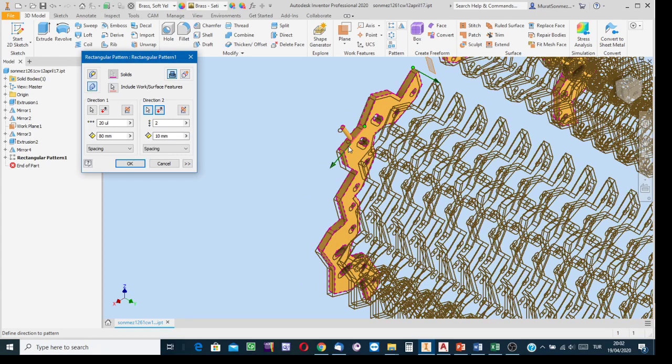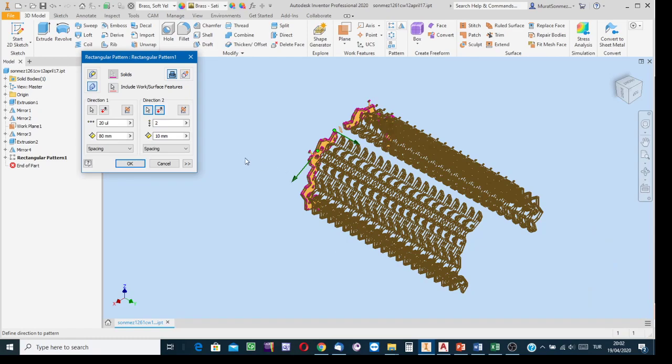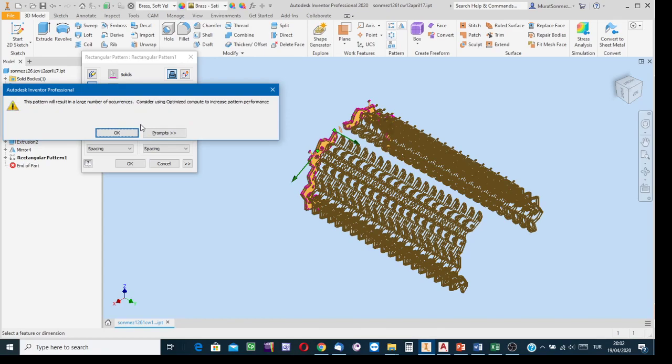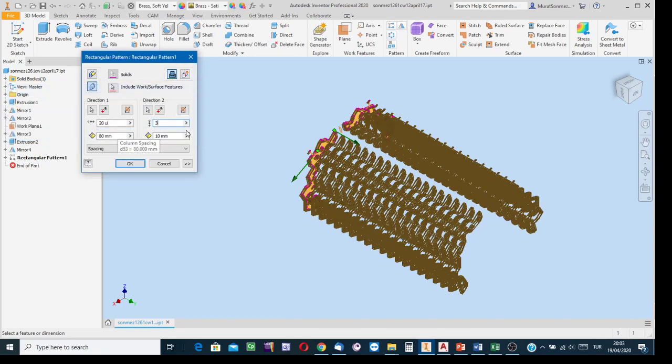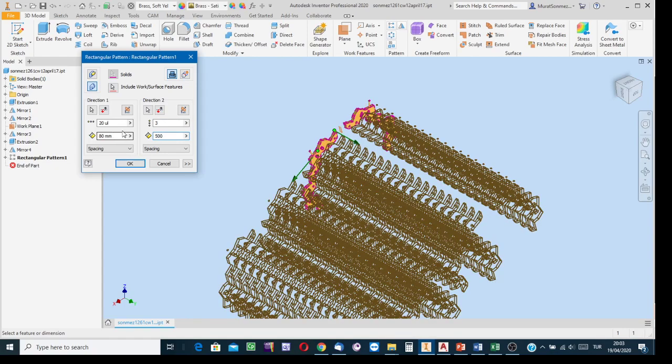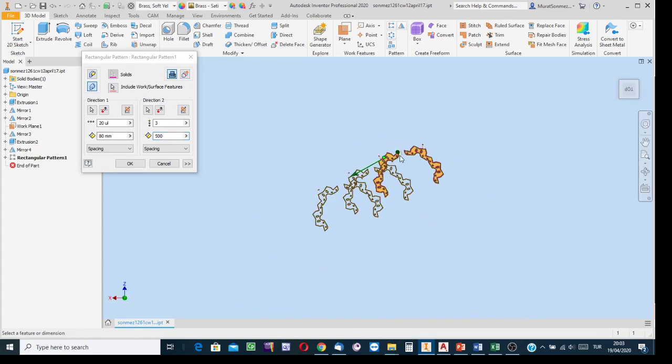This one, for instance, I indicated this, and then in this direction create 3 more columns. Okay, and the distance between them, say 500, depending on the case, of course. Here you see 1, 2, 3, 4, 5. But say 3, 1, 2, 3. Well, I see that the distance is to be greater, say 1000 in this example. You see, and then click on OK.